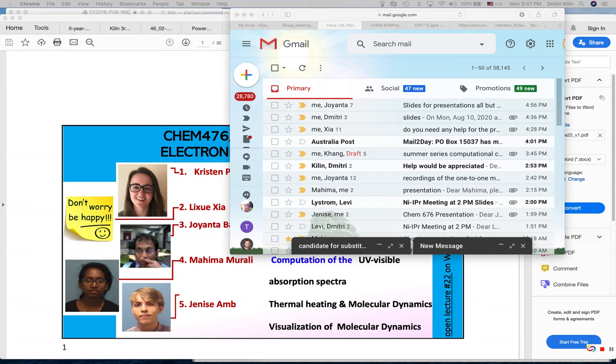Okay. ENCUT, just as I said, you usually have to set the ENCUT equal to or greater than the max value of the ENCUT in the POTCAR. Just as I mentioned in this place, there is a max ENCUT for each element in the POTCAR, right?